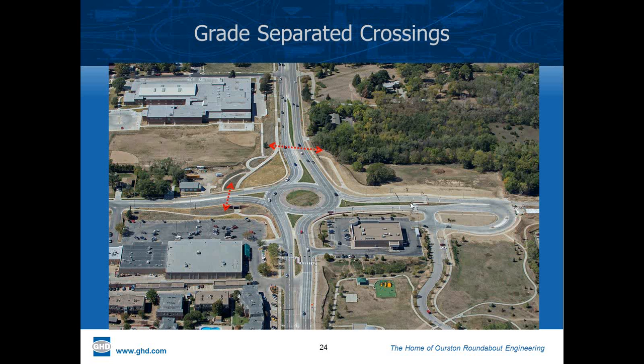And this would be a stepwise crossing in the sense that you push the button to get to the refuge and then you push the button again to cross the second leg. So the signal phasing timing wouldn't give you the complete crossing all in one cycle. You would have to push buttons twice. And I think that's as it should be because there's a bit of a refuge. The pedestrian can wait and push the button for the other direction. Or in some cases, if there are gaps, the pedestrian doesn't need to push the button in the first place, so they'll cross comfortably without pushing the button. The pedestrian tunnel, it just so happened that the grades were conducive to this, that the parking lot grade sets up reasonably well for sight through the tunnel.